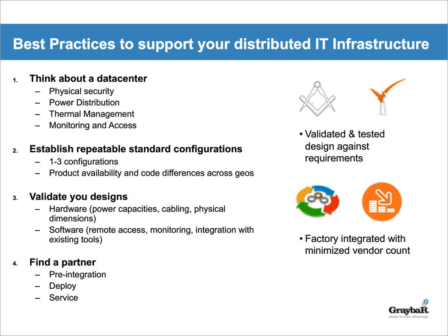If you don't do the power distribution or the thermal management right, you're going to be more prone to downtime, right? Let's say you decide you don't need a UPS. So the power is not going to be filtered. It's not going to be clean power. So any anomaly on the utility power is going to cause your equipment to shut down or even damage your equipment, which will lead to downtime.